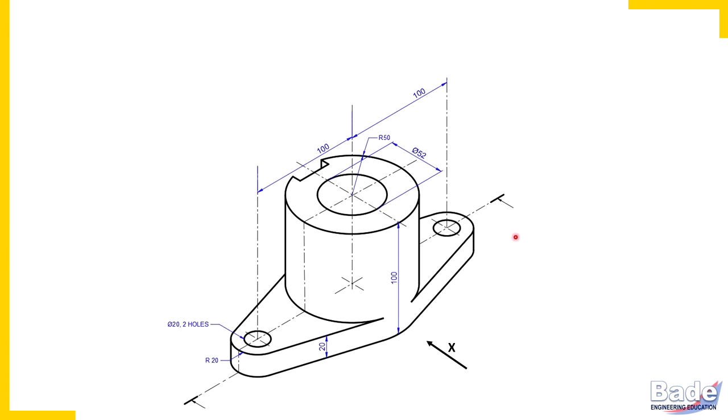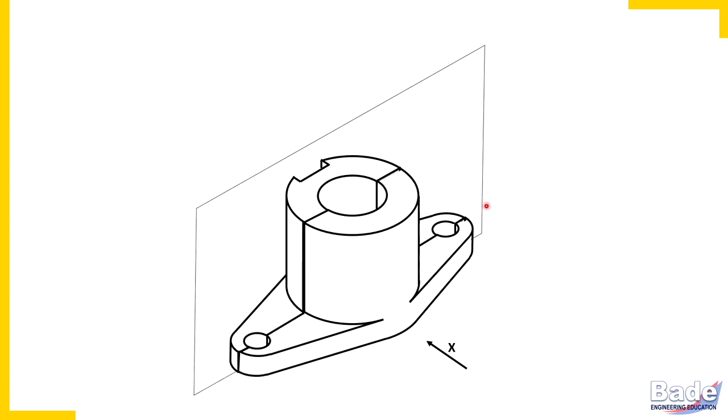Now actually how this object is cut, try to understand. But before I cut this object, once again focus on this center line which has dark end dashes. Now here I have cut this object in two parts by a cutting plane. This is the cutting plane. This cutting plane is parallel to VP. It makes two parts of the object, front side portion and back side portion.